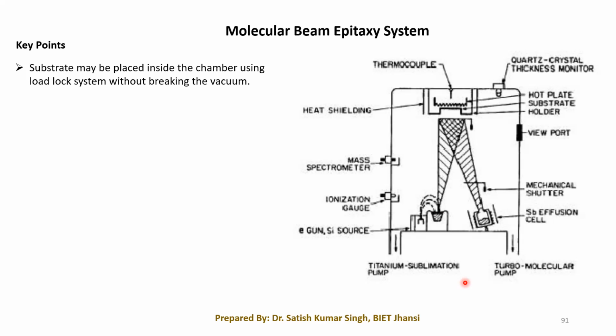That is also very much important, so we have to take care of it. First of all, we need to evacuate the chamber, and then in the next process, we have to place our substrate into the chamber. Okay, so we have to place our wafer or substrate into this particular chamber.